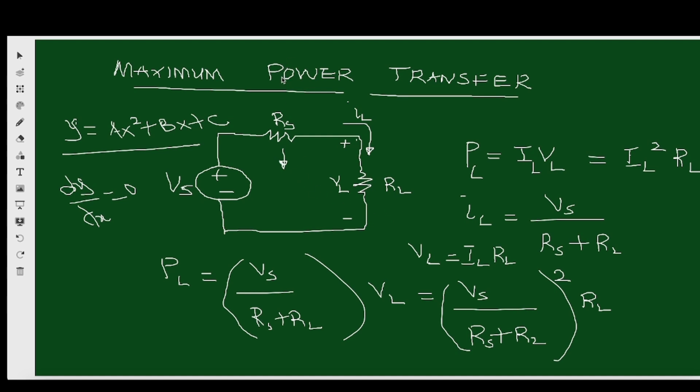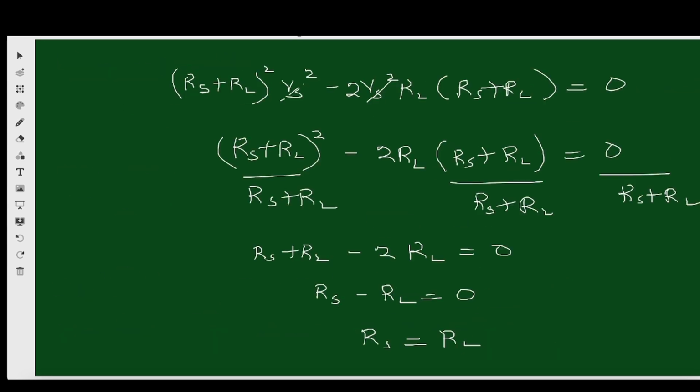So what will now be the value of the maximum power? To state this literally, that is, for us to know what the maximum power transfer theorem states, it states that an independent voltage source in series with a resistance or an independent current source in parallel with a resistance delivers maximum power to a load resistance such that the load resistance is equals to the equivalent resistance.